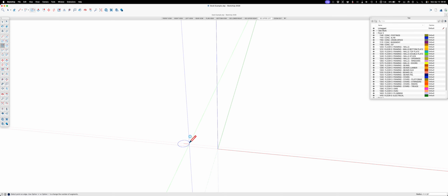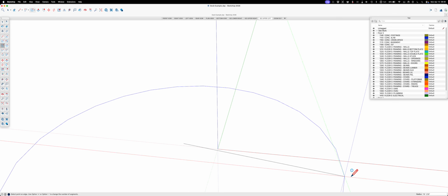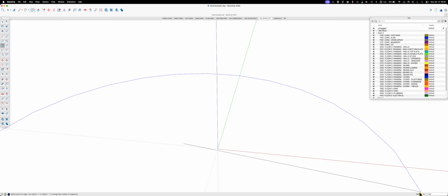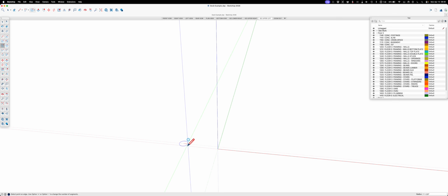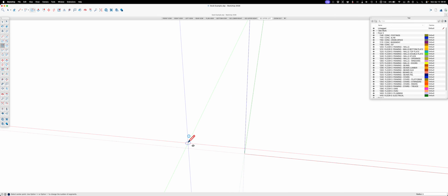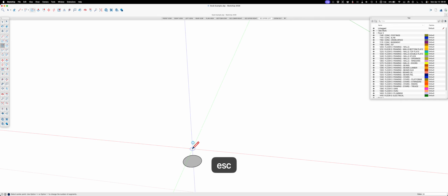So I went to the circle tool and I'm dragging a radius, and as you look down here on the bottom right, as long as I don't click anywhere, I can just start typing. A radius of 16 inches is 8, so I'm going to type the number 8 and hit enter. And there is my 16-inch circle.